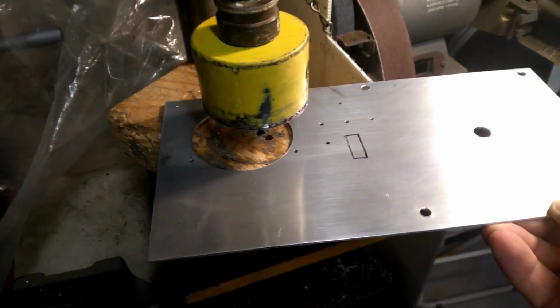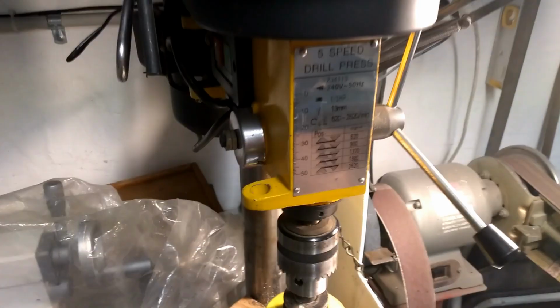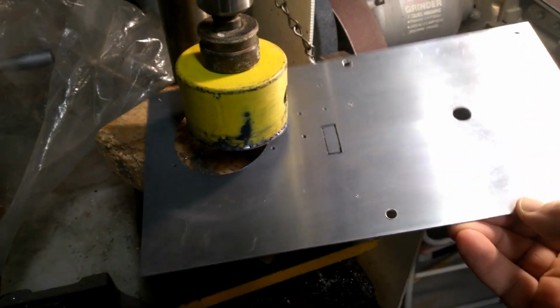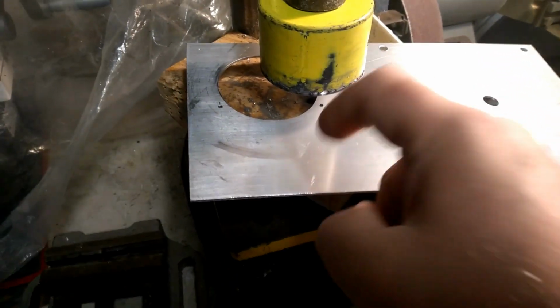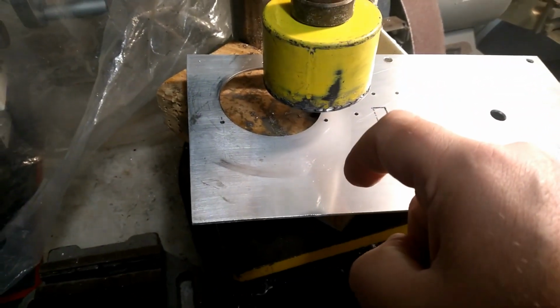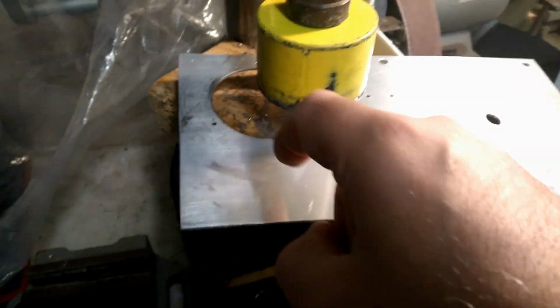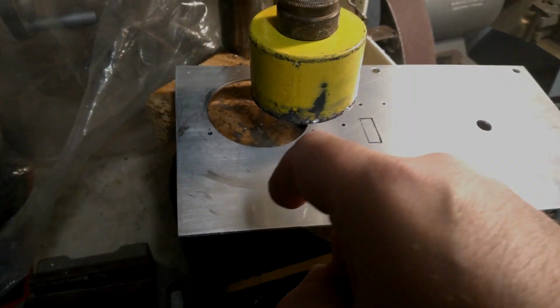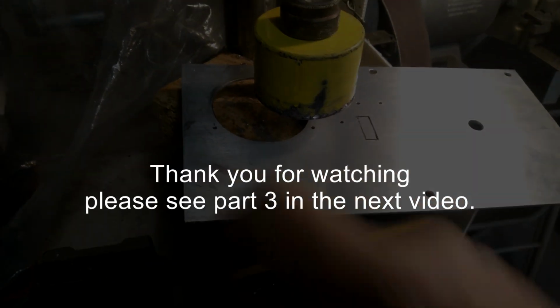I didn't show this, but the holes have been cut with the hole saw on the drill press, and the LCD's hole will probably be cut by drilling holes, maybe running the jigsaw, or drilling a lot of holes, and then when you break the section off, you just file it.